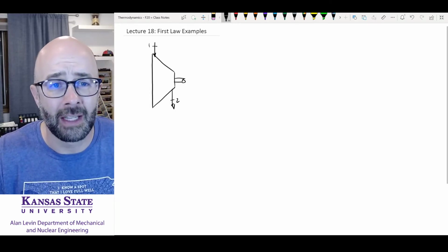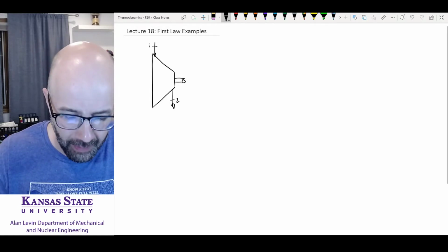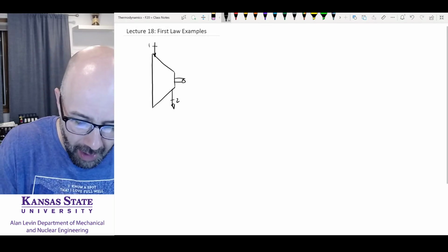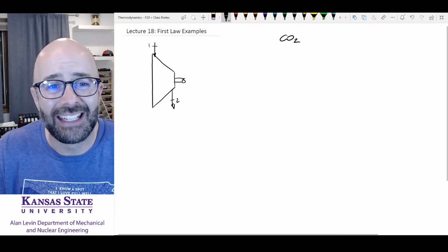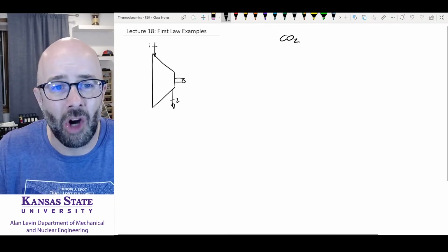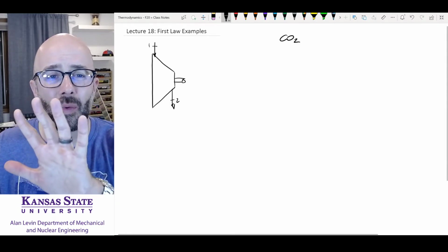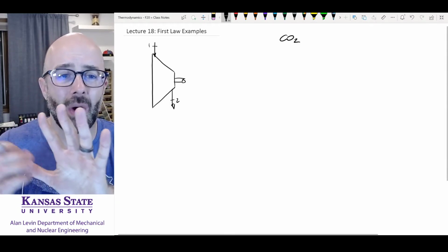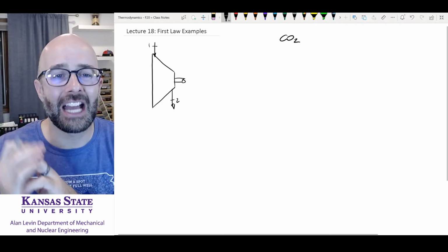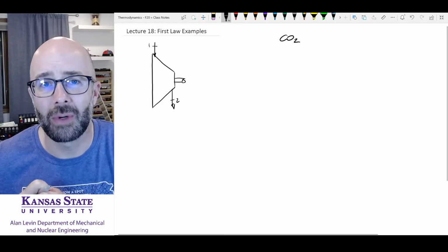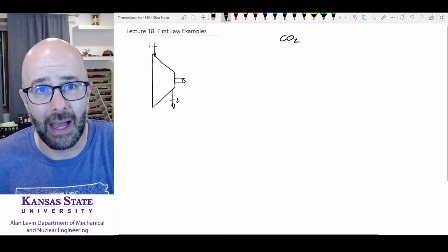And this shaft is saying that we're putting in power into this compressor. And they tell us that we're dealing with carbon dioxide. Carbon dioxide, we're going to treat it as an ideal gas. Remember, carbon dioxide can be treated as an ideal gas, but those 5 things that we have steam tables for: water, ammonia, propane, R134A, R22, when they're in their gaseous state, we're going to look up those properties in those tables. We're not going to consider them to be ideal gases.